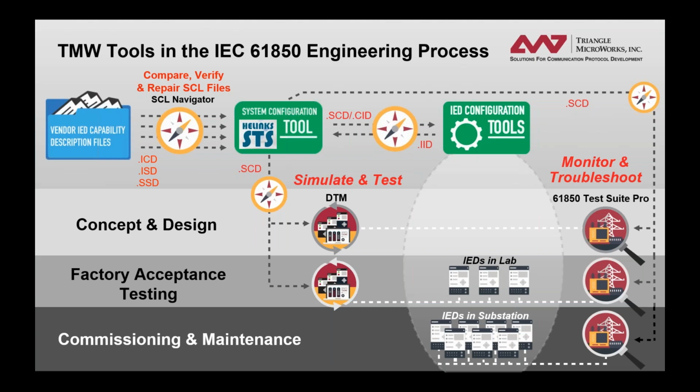For DTM, in terms of timing accuracy, do you measure the latency and jitter of the simulated GOOSE messages? There must be some difference between simulated GOOSE from a PC versus actual GOOSE messages from an IED. Any comments? So yes, DTM solely runs on Windows applications right now. So we do have some sort of restriction when it comes down to the timing requirements of Windows. That being said, where we can, we monitor timestamps and things set by the 61850 device, and we try to be more accurate with timing based on those types of parameters.